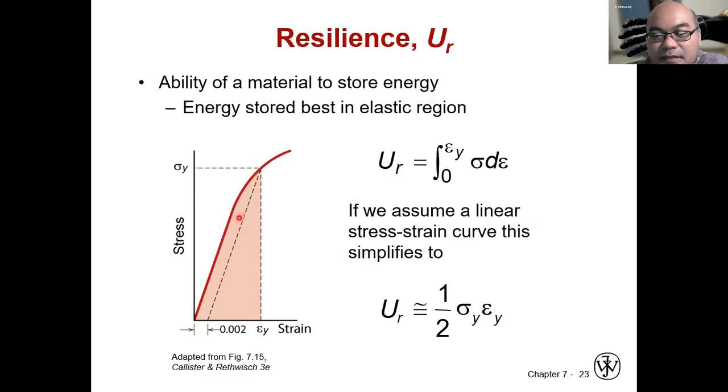If you assume a linear stress-strain curve, this simplifies to half sigma_y times epsilon_y. The resilience is a function of the yield strength and yield strain.